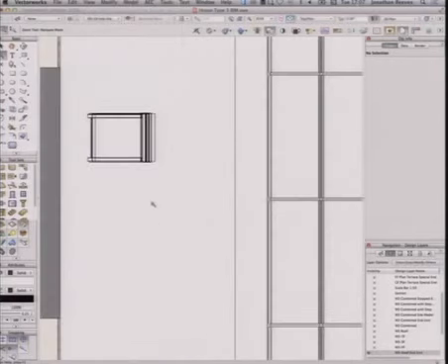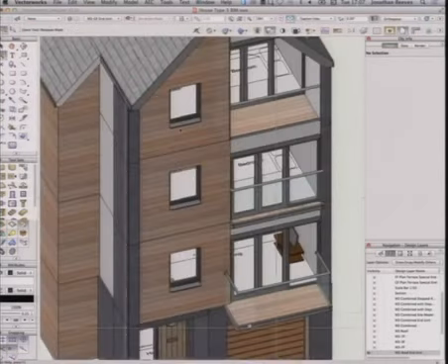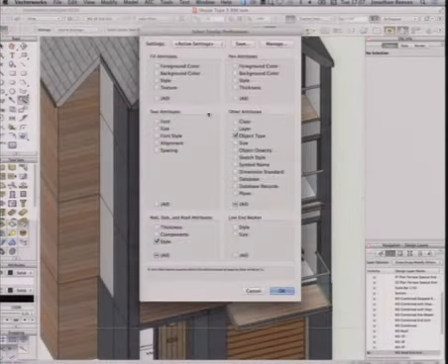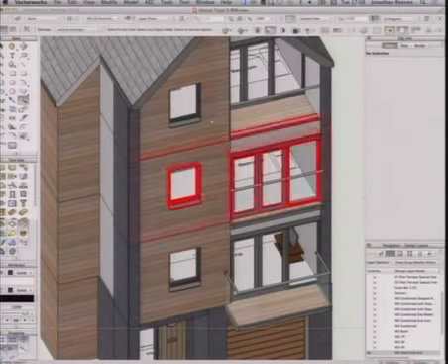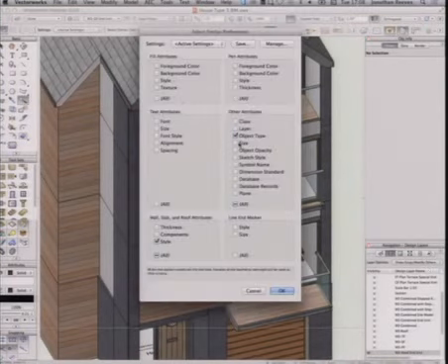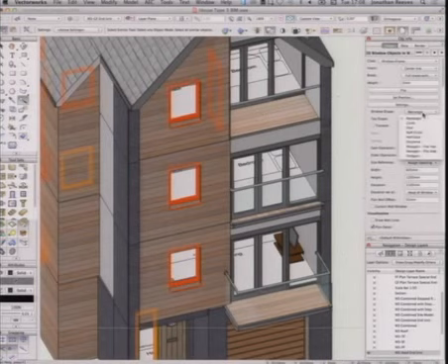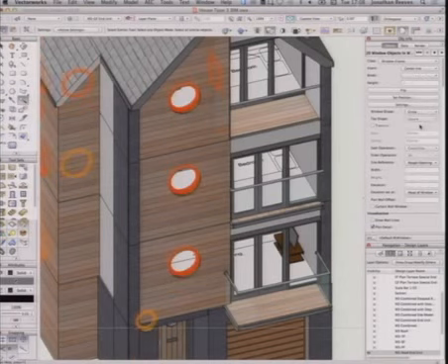Yeah, well, that's exactly what I was doing with the plugins. So, if I click on the window here, get my wand tool, so I'll do object and size, click on that window, as long as I'm on the right mode. Let's turn the size off. Oh, it's because I had something else selected. Let's do that off. So you can see all those windows are now selected, so I can just literally change the parameters of all of them. It's pretty straightforward. Okay. Any other questions at all?